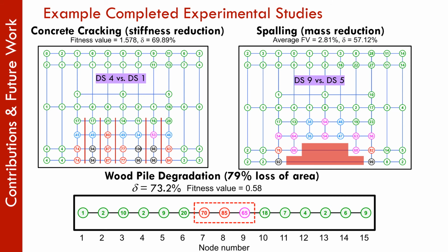We had a 3.5 by 5 foot, 1,200-pound concrete slab, and we induced concrete cracking with a saw, which are the red lines, and we noticed that the damage indication was most notably around those cracked areas and the maximums where they should be.